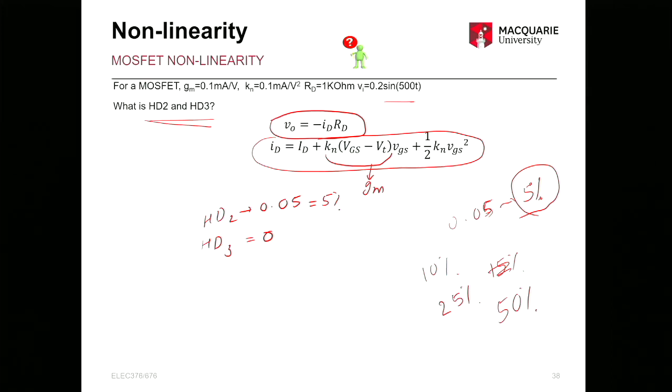So you remember when we did the small signal analysis, we ignored all the DC because DC is only to set the Q point. So imagine in this circuit, you did not have the bias. Say VD was 0, you will be operating here. So you will be operating like a rectifier, right? I understand, I just misunderstood the question.